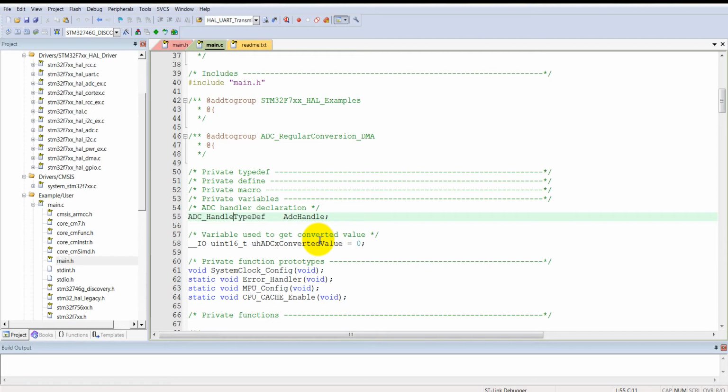So its maximum resolution is 12-bit. So it will take at least 12 clock cycles to convert in the 12-bit resolution mode, and there are 3 clock cycles in the conversion. So it will take a minimum of 15 clock cycles to convert a 12-bit ADC channel.